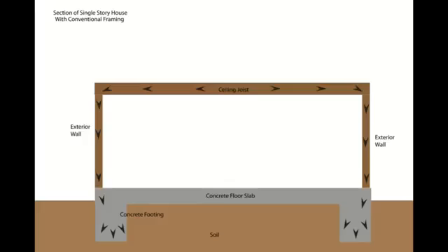So when you're looking at a ceiling or a cathedral ceiling, an open roof ceiling, let's say, where you're trying to figure out what's holding this up, well, it's all of the structural framing members, which also add weight. Don't be confused here. All of these ceiling joists and roof rafters, all the drywall, the insulation, the roofing materials themselves, all add weight to the building and need to be calculated by a structural engineer to figure out what the sizes are going to be for all of the ceiling joists, roof rafters, wall studs, and of course the structural foundations, the concrete footings.